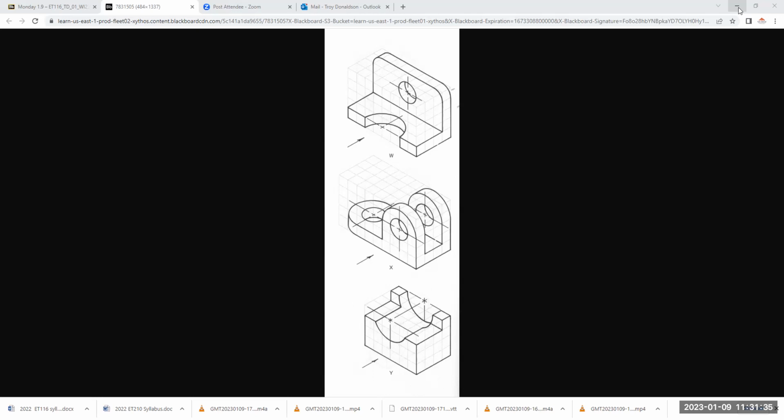And now you can see annotative has already been tweaked. That's probably me. I already have it down to 0.1, right? But if I modify, I can go in and I can change it. I can make it whatever I want. I can get the units, and I could change it to architectural, and now it's going to do fractions. Whatever you want, whatever is required on the drawing. I'll leave it at decimal. I would like 2 places though, not 1.